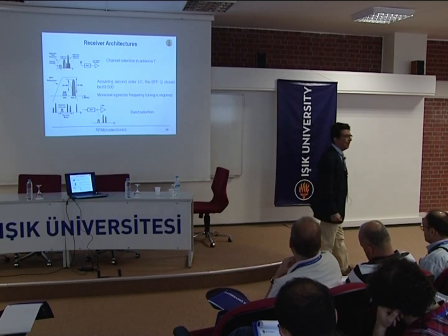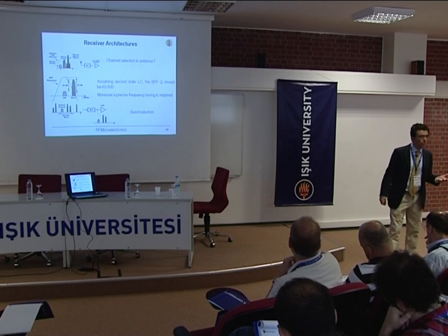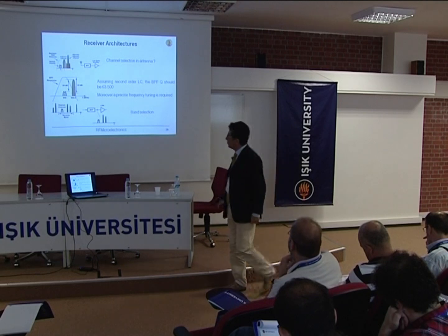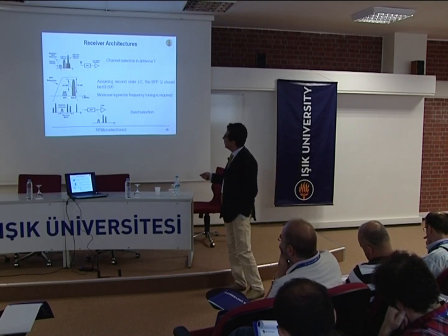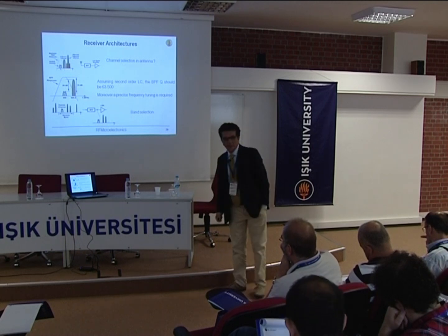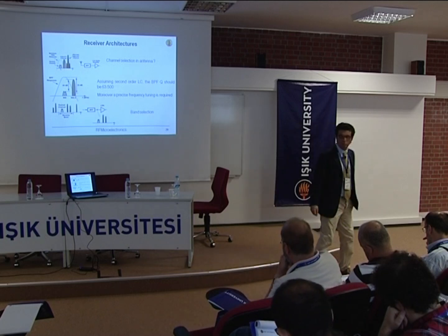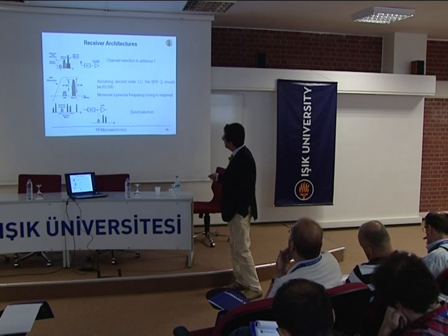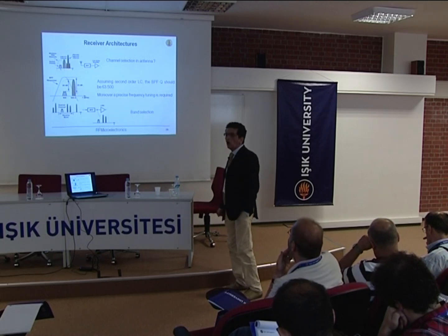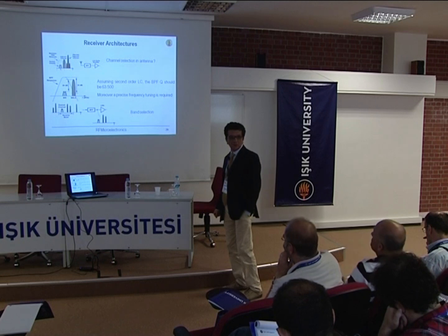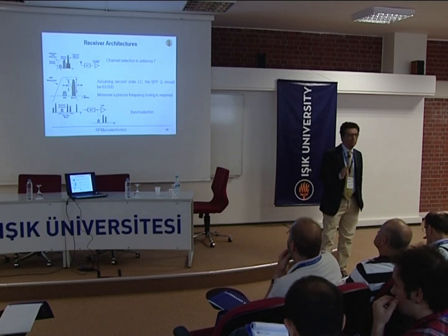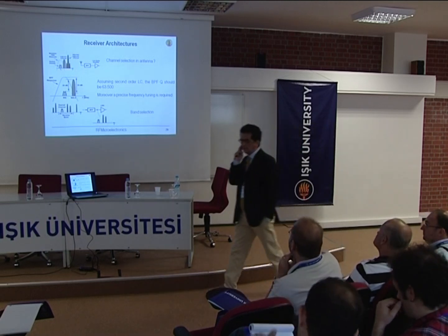By bandwidth, I mean the bandwidth, for example, of a GSM application or any application we can think of, tens of megahertz, but we cannot think about separating 400 kilohertz at 900 megahertz. So we will keep the bandwidth all together, and we will not be able to select anything inside that bandwidth, whereas we can start selecting something which is off the band of the application. So what we say is that we can do a band selection at RF, but we cannot do any channel selection at RF.